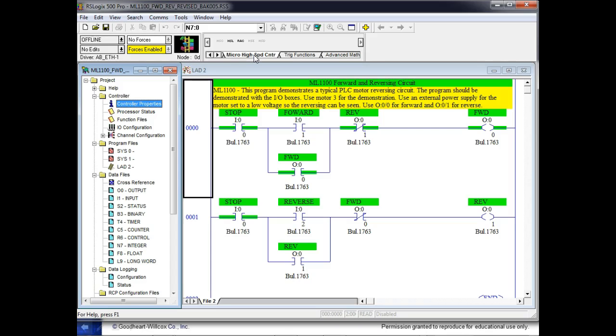So the problem we have now, guys, is we've got encoders that we put on the back of motors to sense the speed. We've got DC motors running at 7,200 RPM, revolutions per minute. You've got an encoder that's got 100 marks on it. Think about how fast those marks are flying past. There ain't no way in the world a software counter would keep up with that. So one of the things you look at and say is, how fast can a software counter go? Since we're dealing with a lot of these encoders on motors, they're starting to put hardware counters in the PLC.